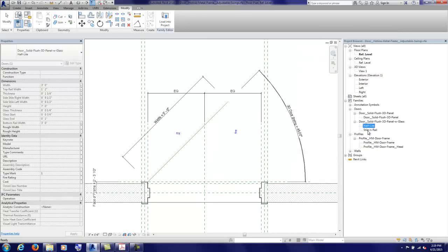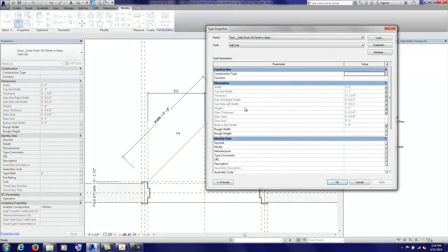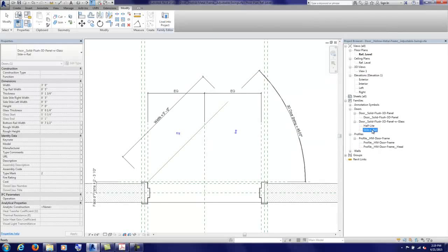And starting to think about it, I guess I could do the same thing with the style and rail, but actually all of these parameters, since they're being passed into the door family, we can set the style and rail door up as a set of parameters. So we'll just place the half light. Maybe let's delete the style and rail out of there and rename the half light.